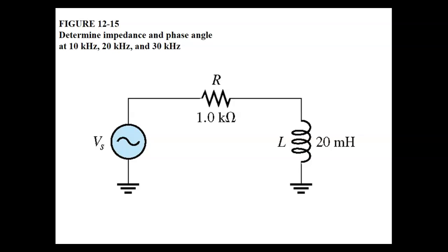So we'd still be using batteries. Batteries put out a really nice DC, but they're not regulated, right? So I don't know if y'all ever loaded. If you measure across like a D cell, you should measure unloaded around 1.65 volts, even though it's supposed to be 1.5. And as soon as you load it, what's going to happen? It's going to drop down because of the resistance of the bulb.